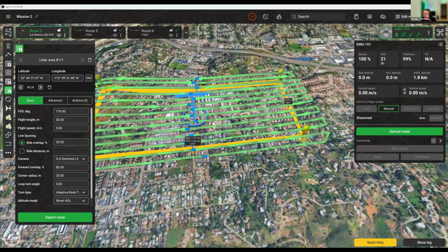So if you have a very small area, or an area where the drone is doing a lot of these altitude adjustments, then the calibrations are not really needed because the drone is moving around enough. The calibrations are needed when the drone is flying on some longer segments without adjusting too much, and then the IMU can, as we call it, fall asleep. And in those cases, you need to have the calibrations.